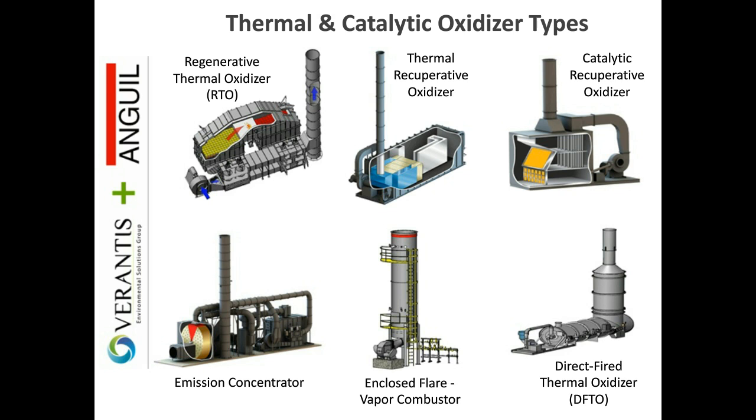I would say 75% of the oxidizers that Anguil sells are RTOs of some variant. The next one over, still on the top, the thermal recuperative oxidizer, operates in terms of the oxidation process the same as the RTO. The difference there is the means in which we achieve the thermal efficiency and the heat recovery, so there will be a slide on that.